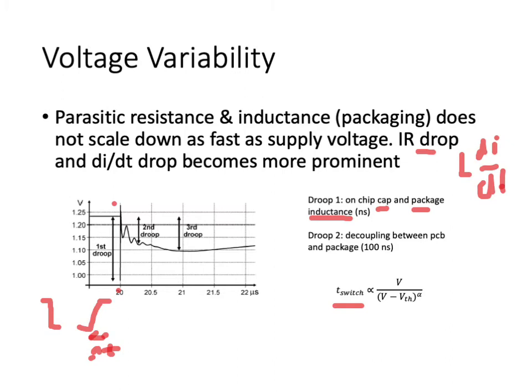But here we're more concerned with the fact that the headroom decreases not enough to compromise the noise margin, but it will actually definitely change the transistor switching speed, because the effective VDD actually momentarily drops due to this parasitic drop, and of course this reduces the available on current of the transistor. So that is this major drop here.